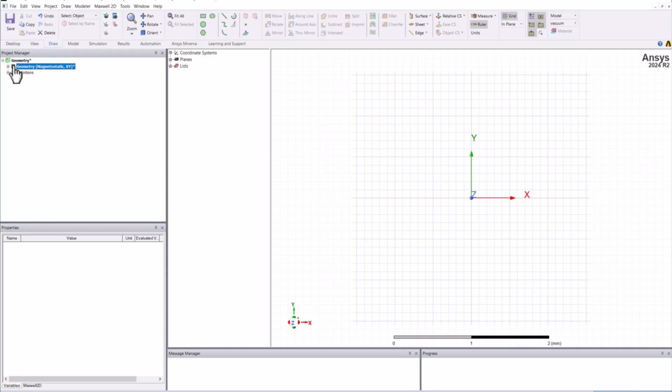For example, if I have created a stator outer diameter as a project variable, and if I am creating multiple designs, say one being a 2D, one being a 3D or any other designs, and if I change the active length or any other project variable that I have defined, that value will be applicable for all the designs wherever I have assigned it. So we have to be careful when to assign the project variable and when to assign the design variables. In this case, we will be assigning only the design variables. So let us start with it.